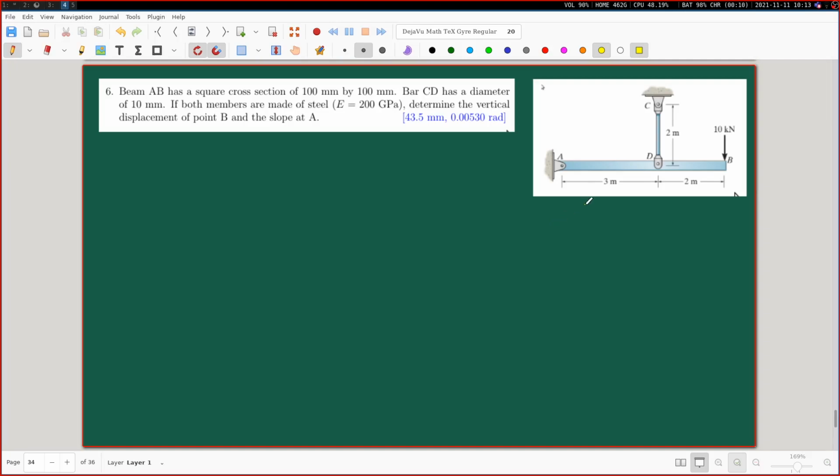So for instance, one may be tempted to think that this is almost like a cantilever beam and this is like a redundant support. But that is not really true, because a cantilever beam would not have a pinned support at the wall. Rather, it would be clamped to the wall. So here, if we did not have this support, this beam would not be remaining horizontal like this, it will be swinging down like that. Okay, it would not be a stable structure. So we do need this bar to support this in this horizontal position. This bar is not a redundant support. So that is one way of looking at it.